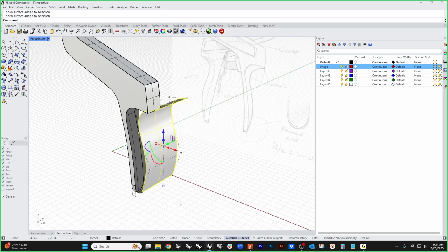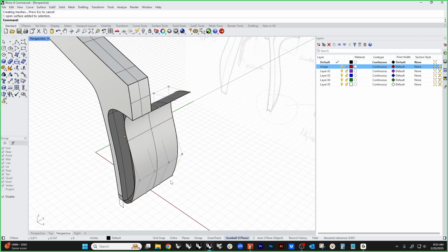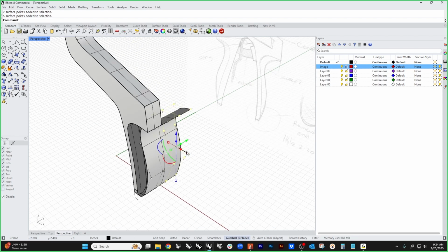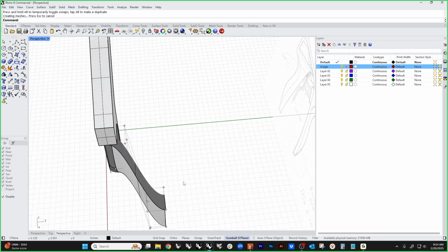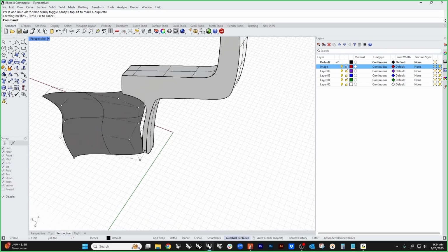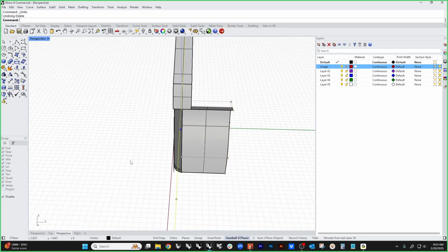We could do the same thing here. If we change degree to 3 and we had 4 points in this surface, and I took these 2 points here and bent them out like this, I could still do the same thing, because these first 2 points are lined up and I could match tangent to that. So this is a proxy surface. I'm going to leave this at 2 points for now.